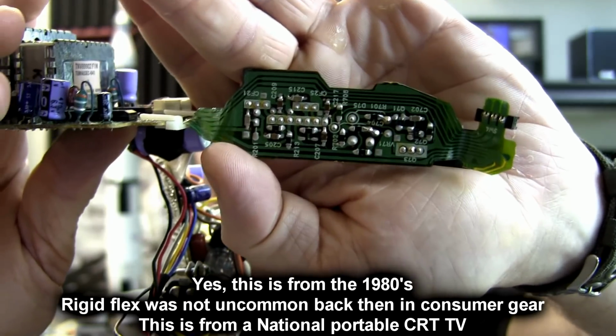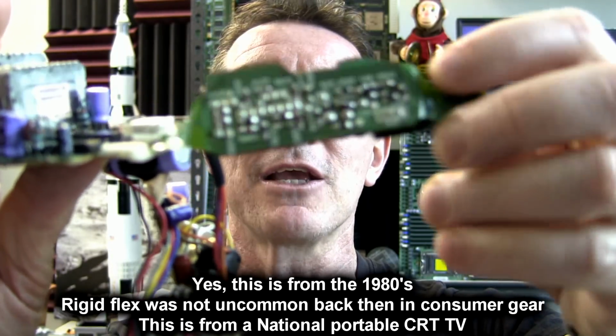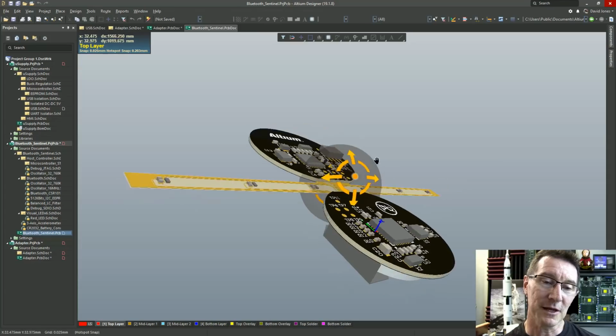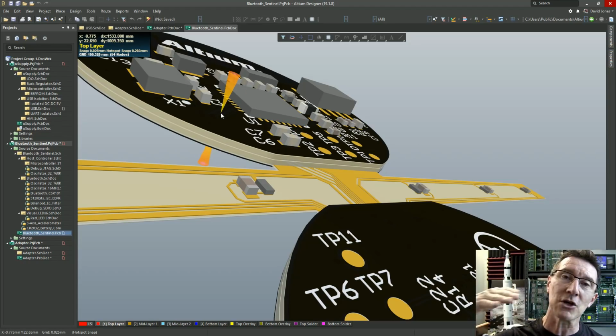It's not in the inner layer, as I said, but it's on the bottom, and then they've got this extra bit over here which then goes off to another board, so it's all integrated, so you don't need the connectors on there. And that's what they're doing here. You don't need any connectors because this Flex PCB here extends as a layer inside the PCB.